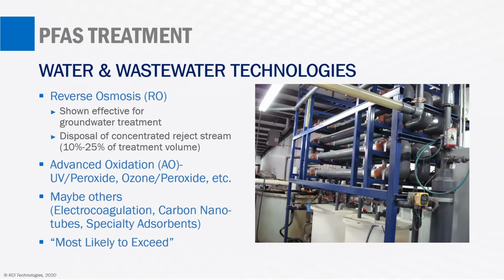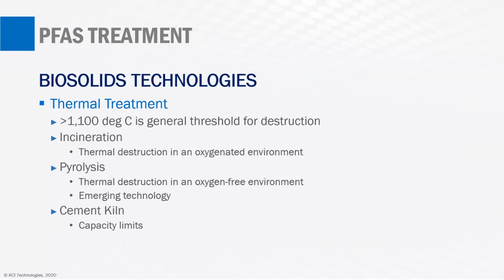So let's turn from the water side of things, and now we're going to talk about the biosolids. So there is some good news on the biosolids front, actually, and that is thermal treatment seems to be kind of the front runner for biosolids treatment. And we can actually destroy the PFAS molecules if we can get it up to 1100 degrees C. Now, there's a lot of energy involved in that, but the good news is we can actually destroy the PFAS.